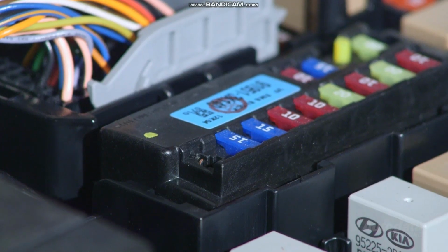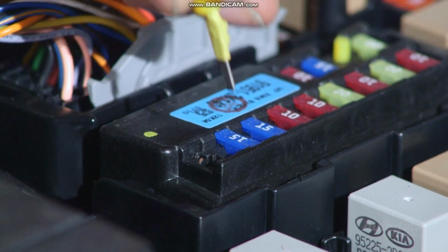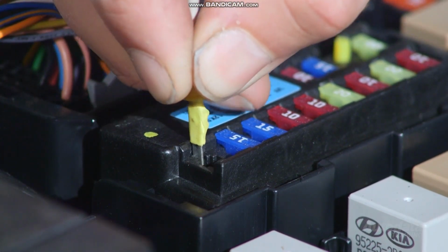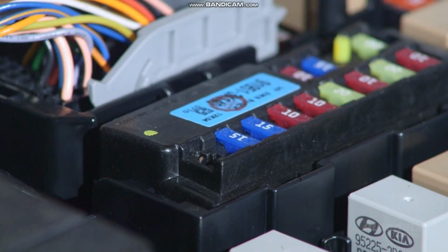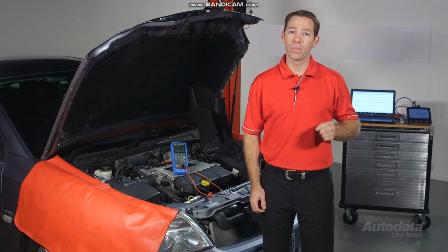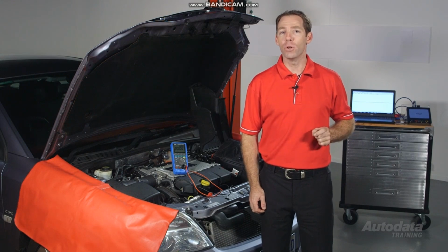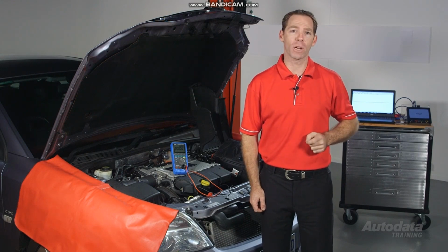If the fuse is OK, test for correct voltage supply to the fuse holder and confirm the holder terminal tension is correct and no corrosion is present. If this is OK, then confirm the supply relay is functioning correctly. If battery voltage was correct and the fuse terminals had correct tension and no corrosion was present, there may be an open in the supply circuit.